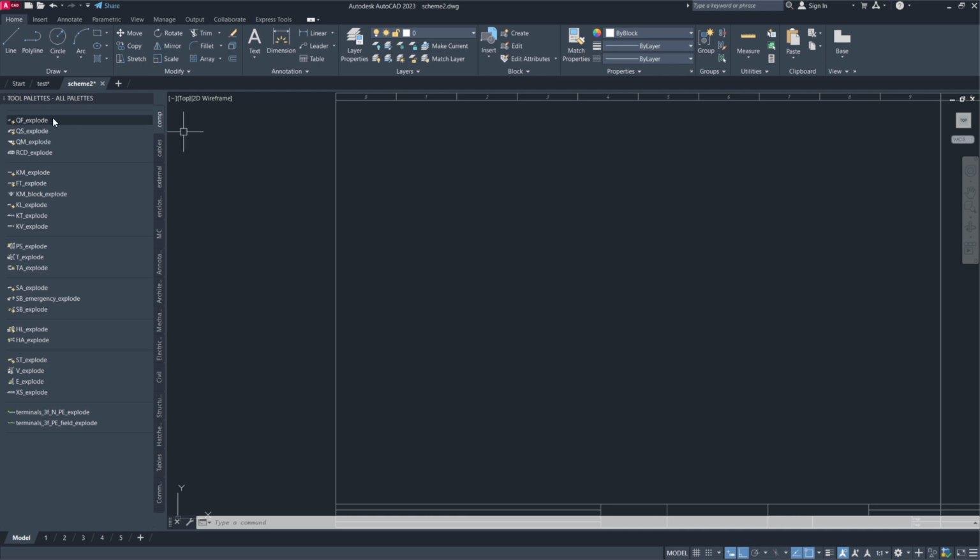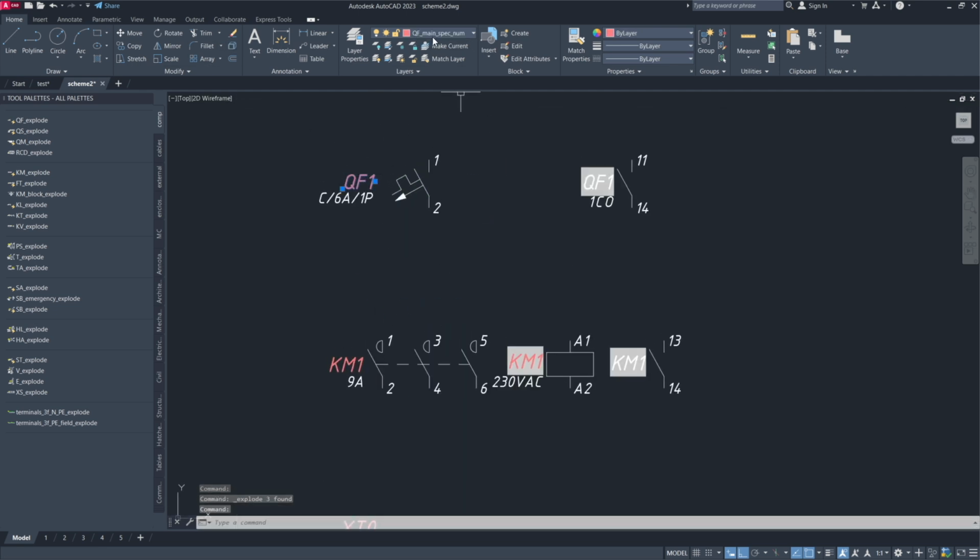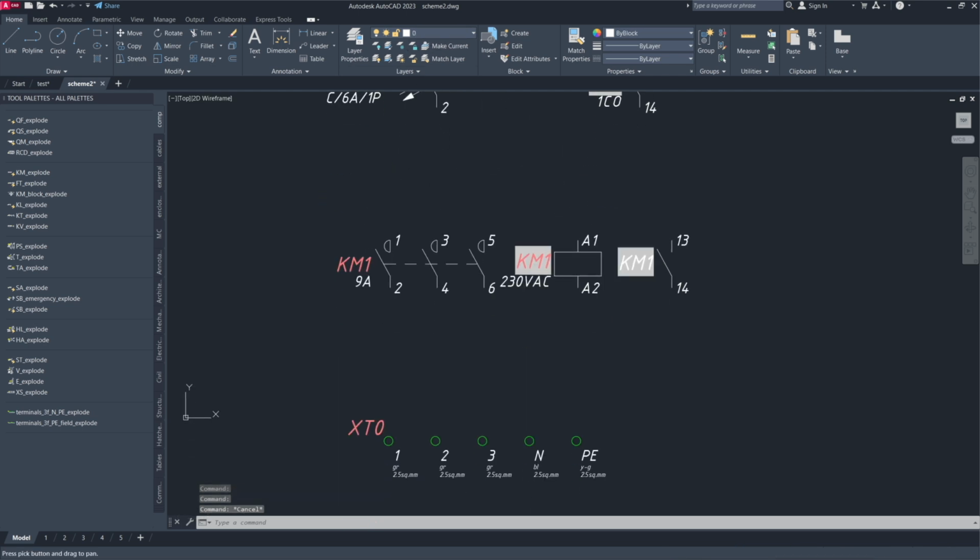All right, time to explain how this works and how you can set up this process in a short amount of time. Let's open a new drawing, insert a few different components, and take a look at what their labels are made of. Pay attention to the layer names. They're the key to how information is collected from the drawing and turned into reports. The easiest way to create a new component is to take a similar one and simply adjust the layer names.